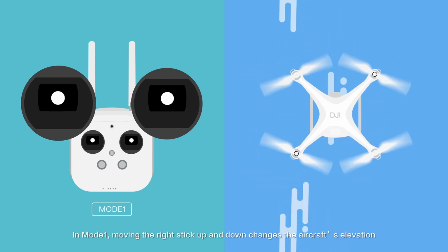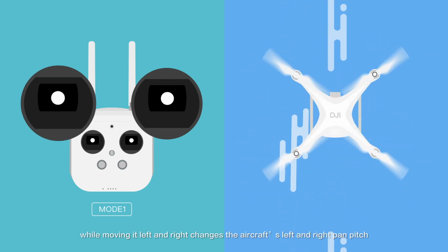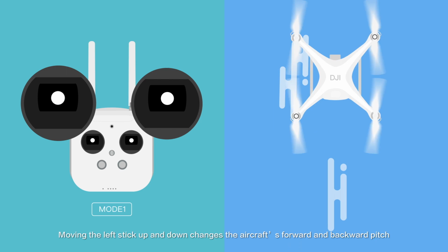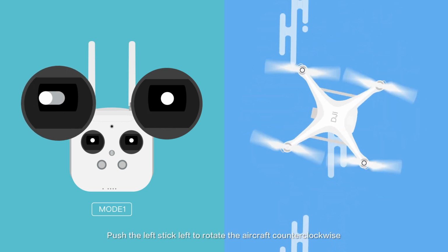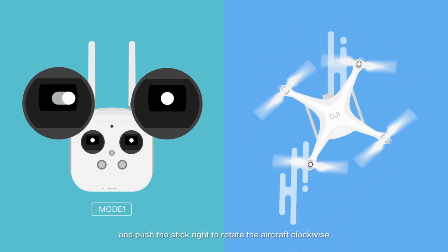In Mode 1, moving the right stick up and down changes the aircraft's elevation, while moving it left and right changes the aircraft's left and right pitch. Moving the left stick up and down changes the aircraft's forward and backward pitch. Push the left stick left to rotate the aircraft counterclockwise, and push the stick right to rotate the aircraft clockwise.